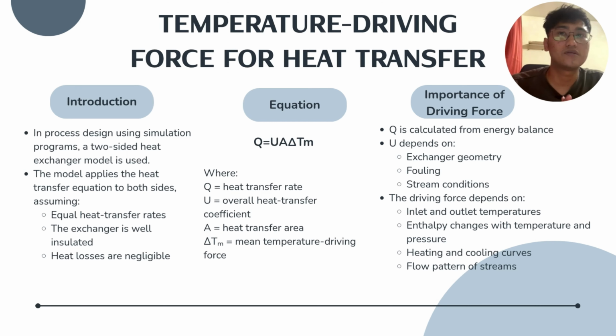I will explain the concept of temperature driving force for heat transfer and pressure drop in heat exchanger. In process design, especially when using simulation software, we typically use the two-sided heat exchanger model. This model assumes heat transfer rates on both sides are equal. The heat exchanger is insulated and the heat loss to the surroundings is negligible.